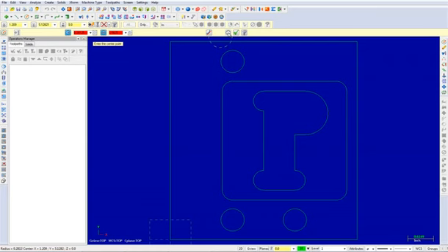Finally, select the fastPoint icon once more. This time, input the following coordinates, 3, 4.5, and select the OK button to exit the command. Press enter. The fourth arc will appear as shown. You can now choose the OK button to exit this command. Your geometry will appear as shown up to this point.